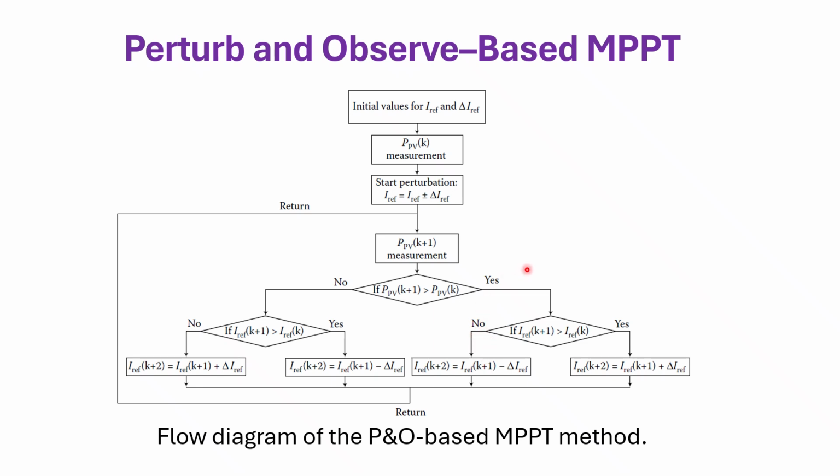We have seen in the curve that this is the current at the maximum power point. On the other hand, choosing an appropriate incremental step for the I reference, del I reference, can quickly approach the operating point to the maximum power point, MPP. This process should be repeated again and again until the maximum available power from the PV array is obtained. The oscillation can be minimized with smaller perturbation steps. However, small step sizes cause a slow response of the MPP tracker.